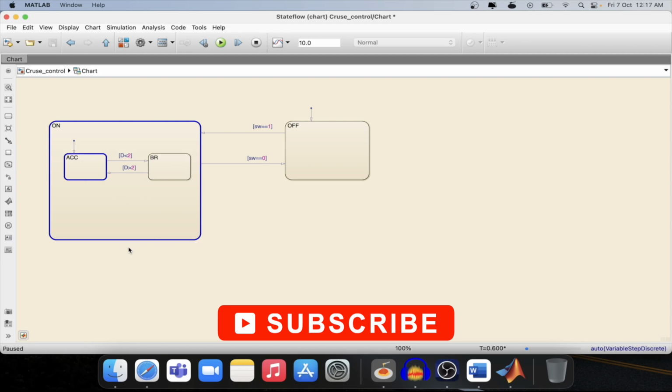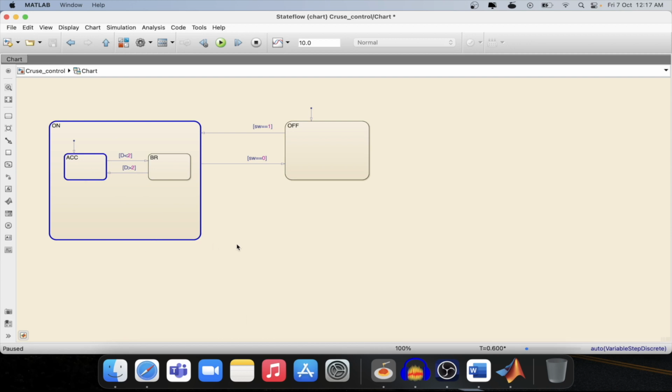So this is how the Stateflow model will be working for a cruise control system, and we have built it based on the requirement document that we have. First, the default stage will turn on in the initial sample time. We have observed in this particular tutorial that the default transition will activate when the system turns on, which is at the initial sample time, and in the next sample time, if the conditions are satisfying for taking the transition, then the transition will happen to the other state.